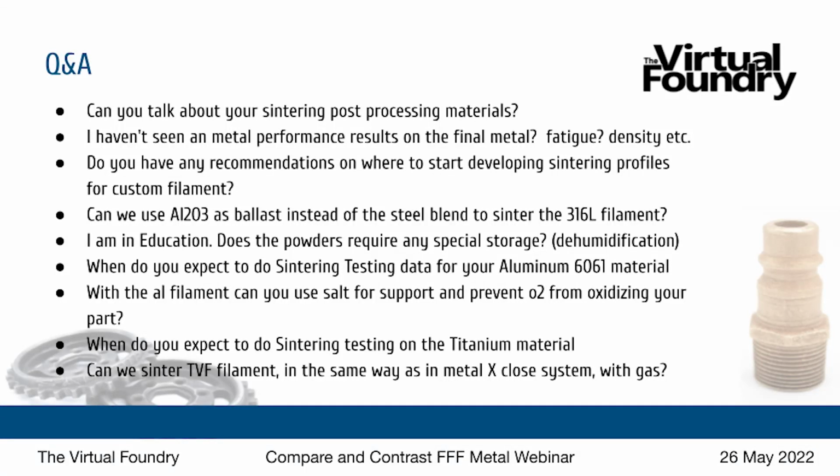Yeah, this is tricky to answer. The short answer is yes, I've done it. The problem is that when we were doing this, we had failures that I couldn't explain. When we went from just using the Al2O3 to using Al2O3 blended with graphite, which is what the steel blend is, our failure rate dramatically dropped, though we don't fully understand why. So yes, you can do it, but your chances of succeeding go down slightly.